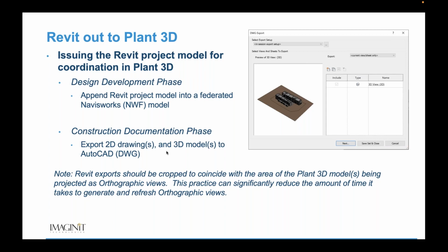So using the NWC file in this case, again, as I said, at the design development phase, I think it's a great time saver, and I know several clients that I've talked to don't particularly care for it because it's very limited at this point in time. I can't snap dimensions, I can't snap the points, and those things will get better as time goes on. But I think there is still a definite advantage because of the capability of refreshing directly from the source model as it changes.